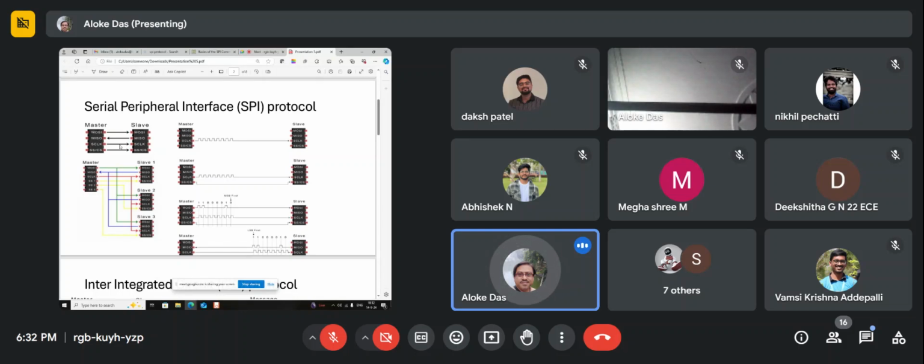And also the clock reference is given. Based on that clock only it can send. Why is the clock needed? Because sending data generally needs a register, which is a bunch of flip-flops connected as a shift register. And when you clock it, at each edge of the clock, the data comes out from that register. So that is the arrangement here, and so the clock reference is needed.